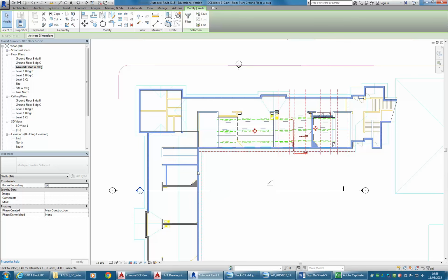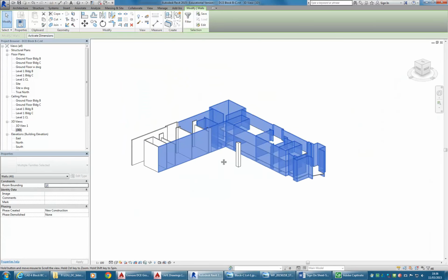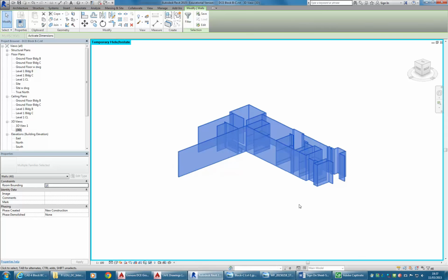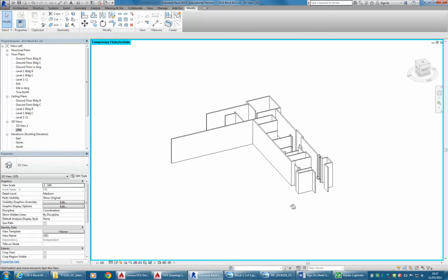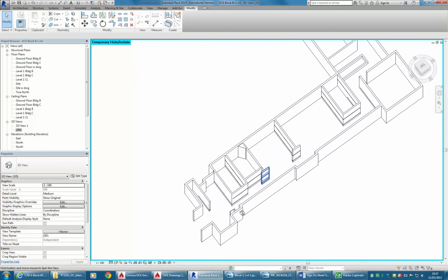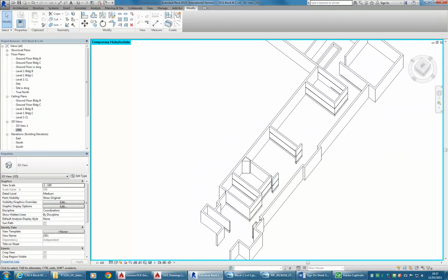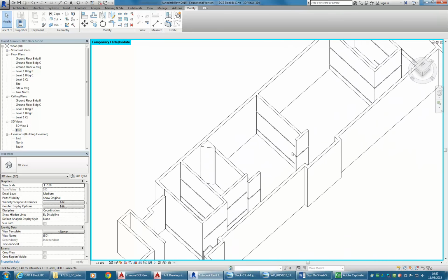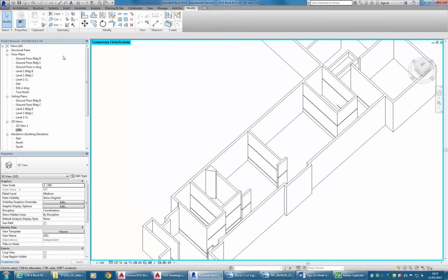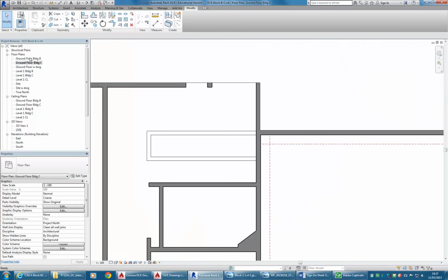I've got different kinds of walls selected, so I'm going to have to do an extra step here. Go to a 3D view, and then using the temporary height isolate element, and now I can check to see if any of those walls are stopping low. So yeah, so they're actually not attached, they're only joined, which is what I'd normally do. It's just strange that it's showing.